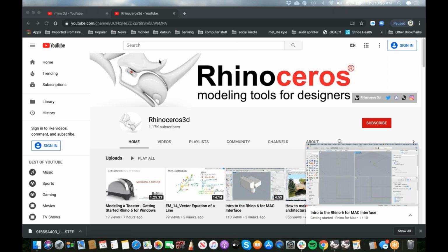But in order to have it unroll cleanly, it would all need to be developable surfaces. And there's a setting for that when you do Loft. So we would build that grit section differently. We would build it with Loft and we would use it developable. And then the shapes would be a little bit different, but they would unroll or Smash or Squish nicely. So, any other questions?